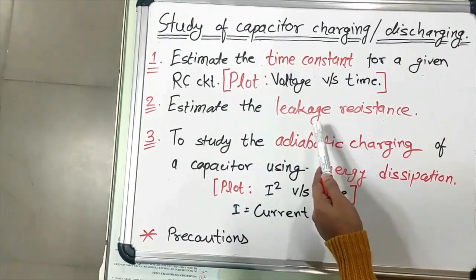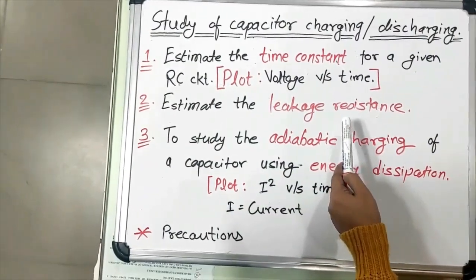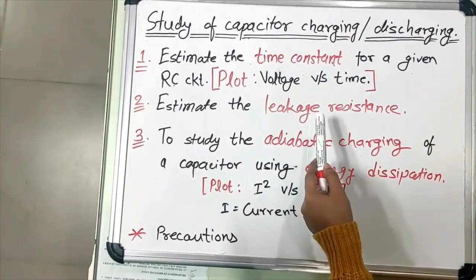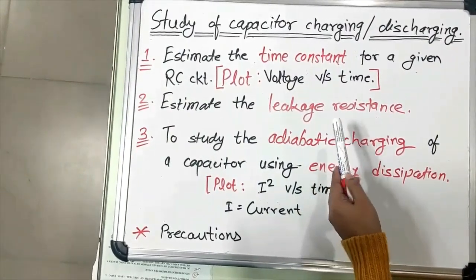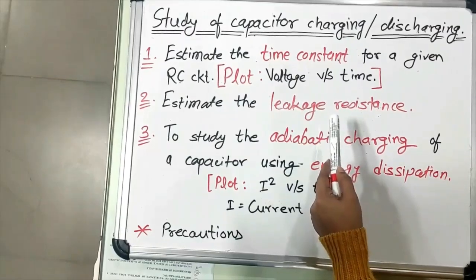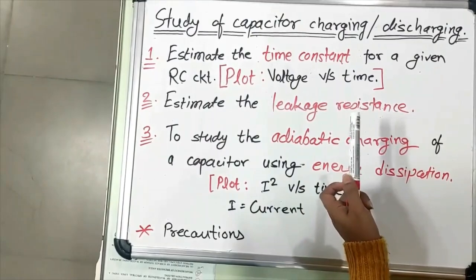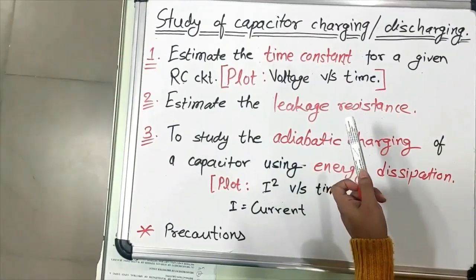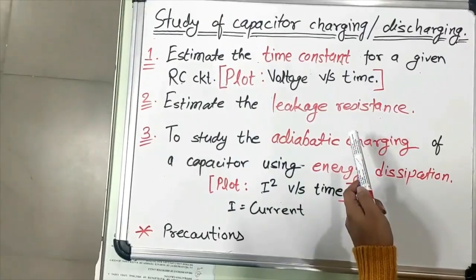Ideally, the resistance of a capacitor is infinite. But practically that is not possible, because they do not maintain the charges indefinitely, and therefore there is always a leakage resistance. In our experiment, you will see that the measured leakage resistance is of the order of mega ohms, which is very high compared to the values of the other components presented in the circuit.